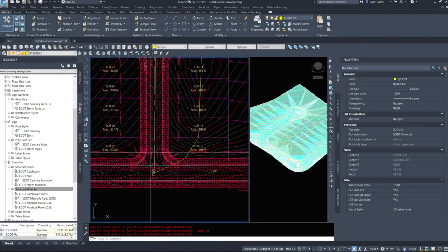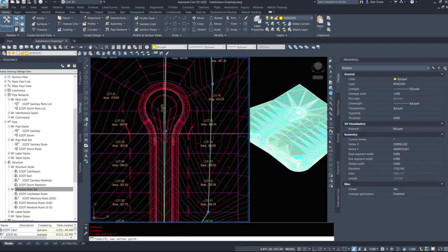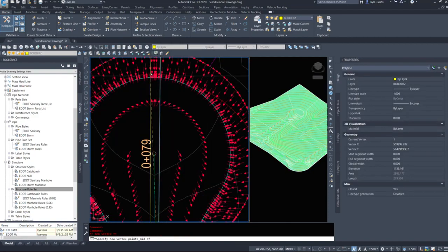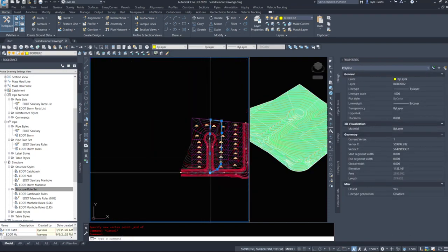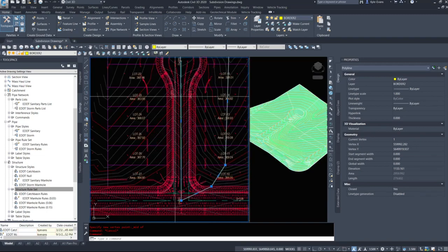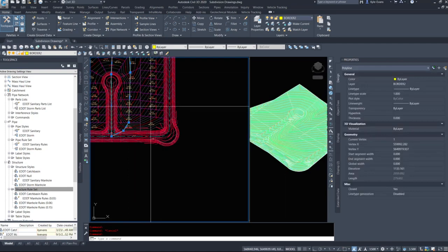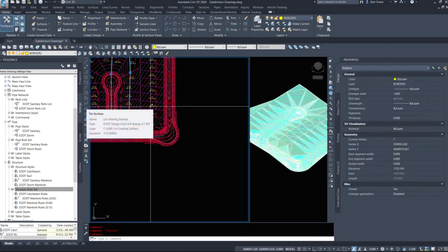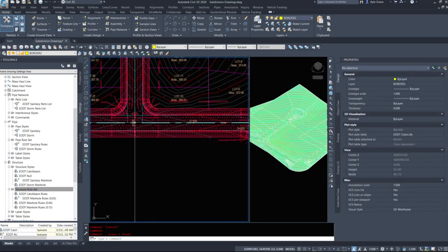I'll close that. However, I should add a vertex from there. This is about, like I said, 3,000 square meters. So we can add another catch basin right here to handle 3,000 square meters. And that leaves this area to be 7,000 square meters. So we have cut our area in almost a third here by adding one catch basin where there's already an existing manhole.